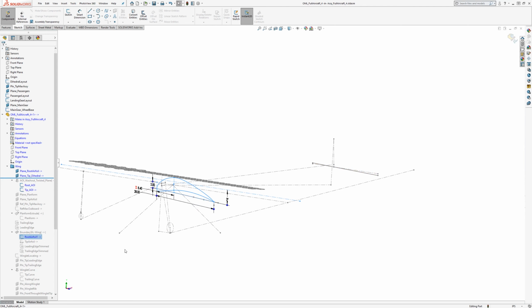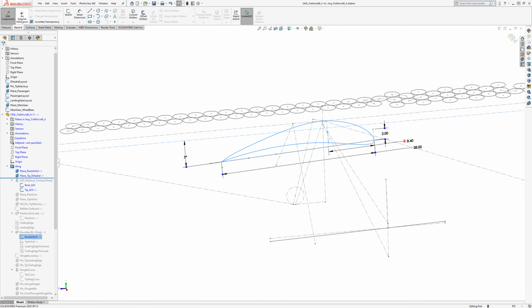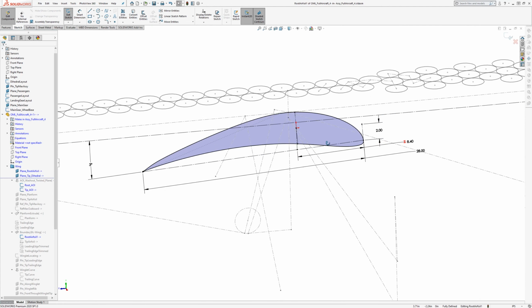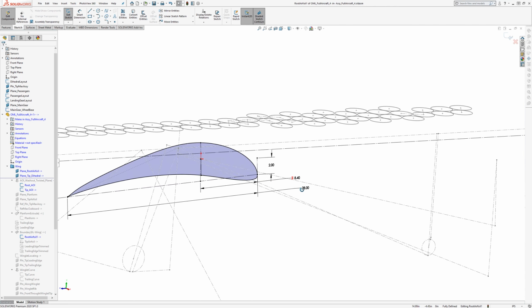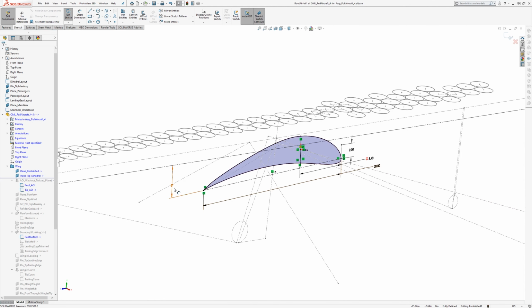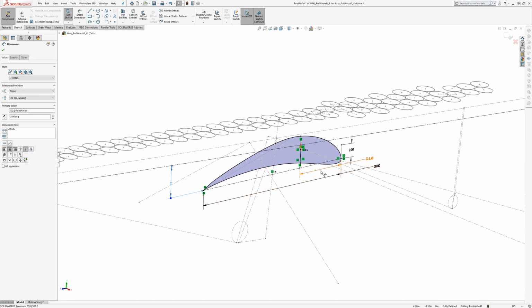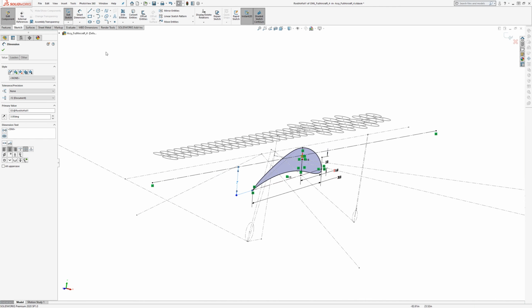We have the root angle of incidence. Well, actually the first one that I put in is this root airfoil. So all that is the airfoil that has its midpoint of a certain percentage of its chord pierced to the dihedral layout line, and then we make sure that it has an angle of incidence and a chord length, and that's pretty much it for the root airfoil.